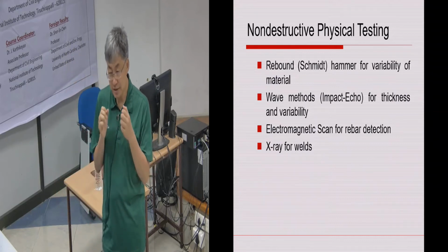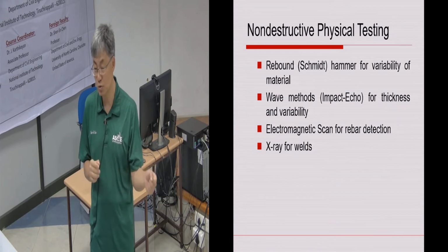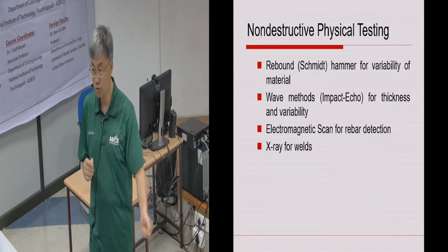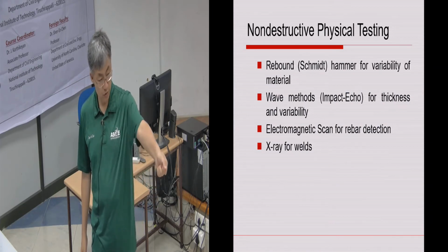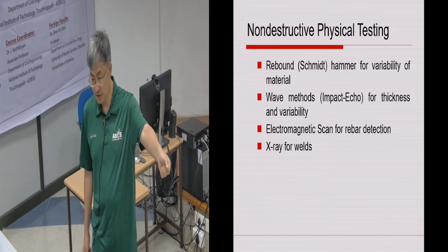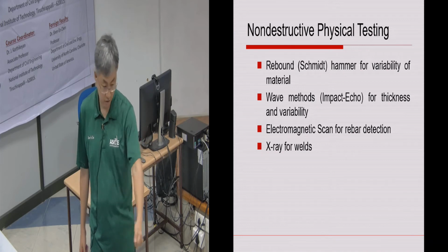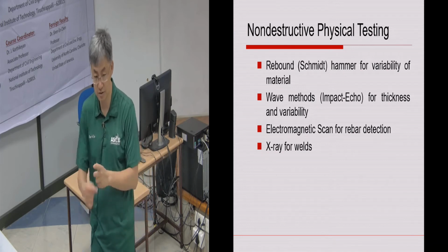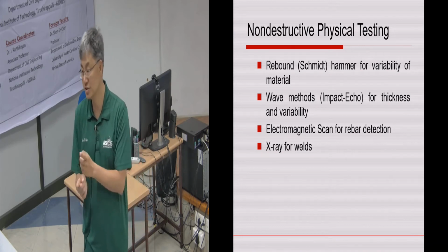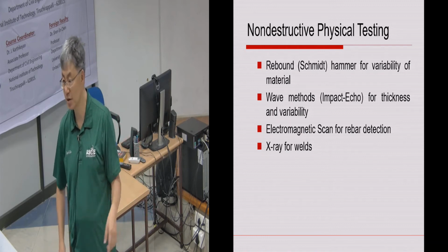But then those tools are only as good as how you perform. Those rebar detectors usually are very sensitive, so you have to roll it in a certain way, okay? And you cannot change direction, because if you change direction, then the data XYZ becomes different, okay? Then your data becomes very bad, okay?